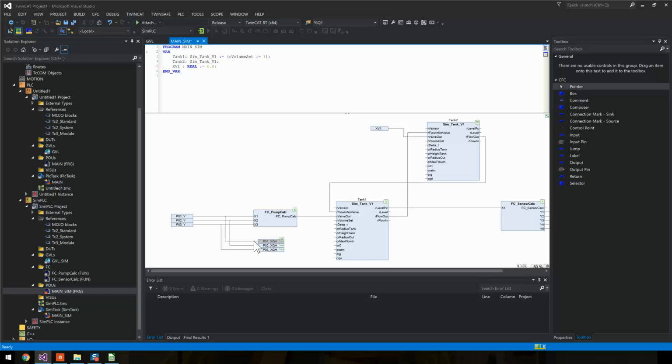If we could place this one at the flow, so if we turn on pump 1, and the flow going out of tank 1 is something we'd expect by turning on pump 1, we can use pump 1 confirmed running as the flow is actually what we expect.